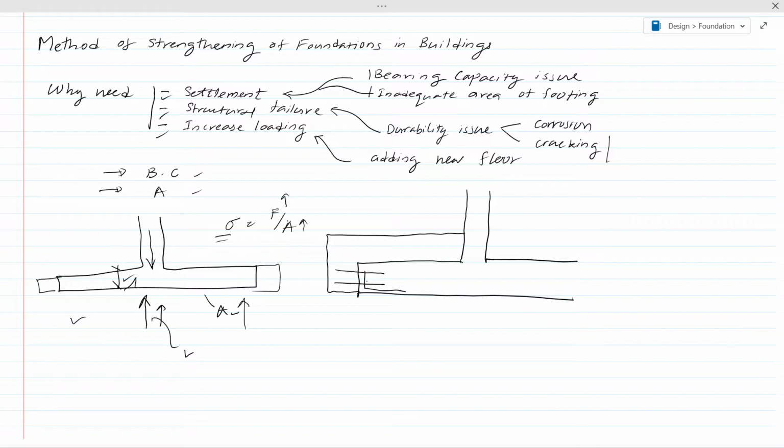Then it could also continue to take the bending moment, because this bending moment won't be that high in this section. The bending moment will be maximum there. So these dowels you can insert like this, and you have to maintain the adequate anchorage length. So you have to bend the reinforcement depending on your anchorage requirement.